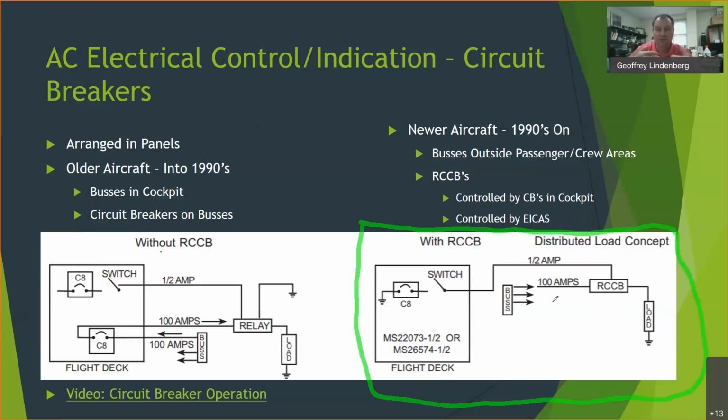It just feeds into the wings to the center point of the aircraft, the wing ducts area. That's where the main circuit breaker and contactor is that supplies power to our heavy loads: cooling fans, electrically driven hydraulic pumps, electrically driven fuel pumps, and on and on.